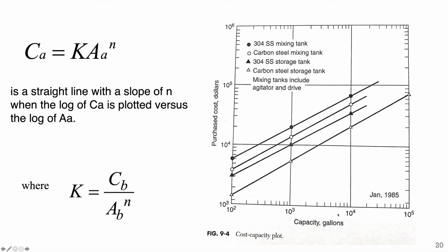So here on the right side, you have the gallons here. Notice that this graph is in log form. So you may have log-log axes, or you may have log-linear form. Please be careful while reading this, okay? So here you have 10 to the 3 gallons. This is the capacity for this equipment. Also notice that it corresponds to a unit cost, which can be related here. And that factor you can use to calculate your particular cost for the desired equipment.